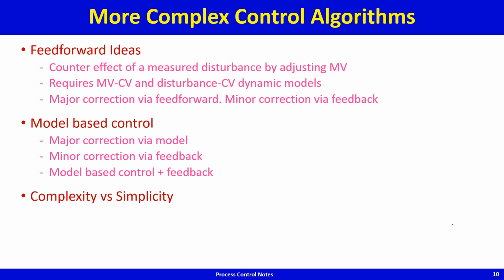You use a proportional controller, and now you need to access intermediate values between maximum heater duty and 0. So your equipment will have to be a bit more sophisticated. But then proportional control results in offset. You can expect offsets. So you say, okay, we'll implement integral action. Your controller is becoming more complicated.